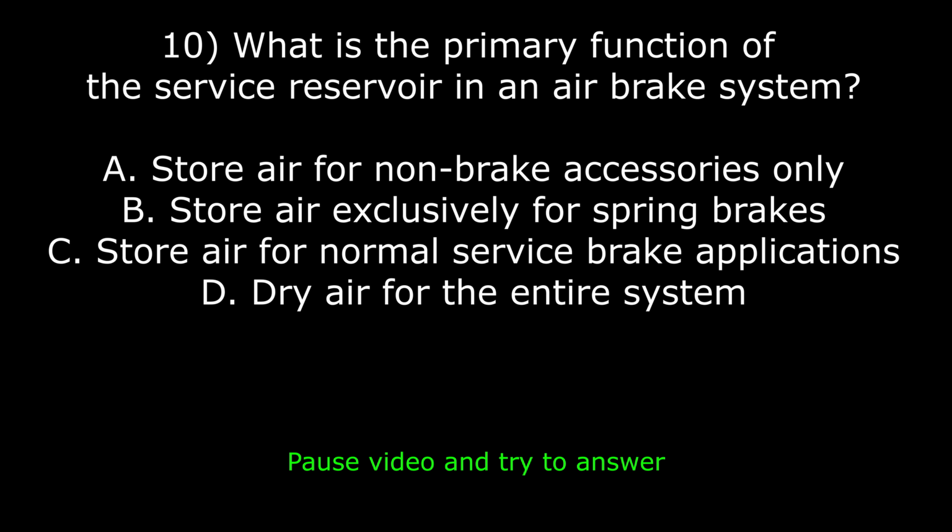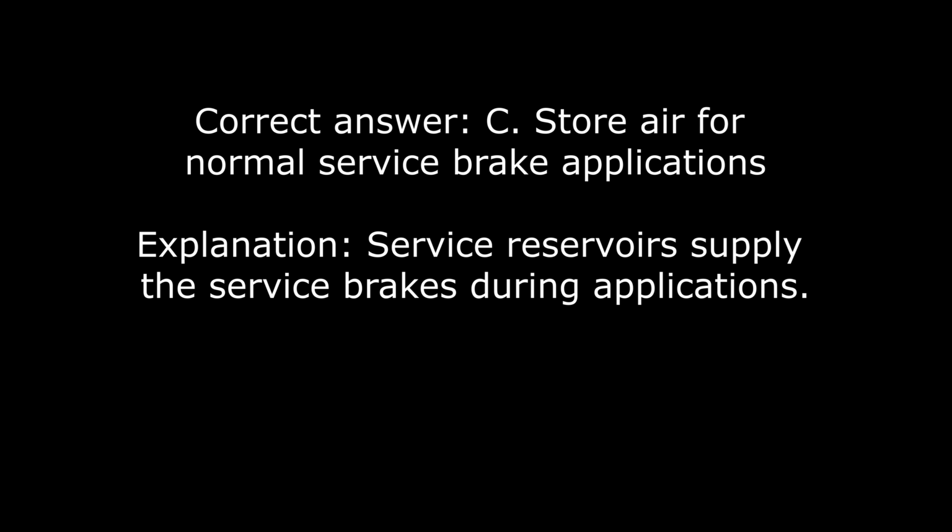10. What is the primary function of the service reservoir in an air brake system? A. Store air for non-brake accessories only. B. Store air exclusively for spring brakes. C. Store air for normal service brake applications. D. Dry air for the entire system. Correct answer: C. Store air for normal service brake applications. Explanation: service reservoirs supply the service brakes during applications.